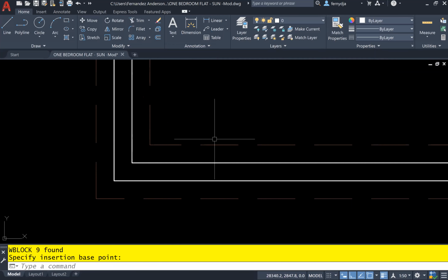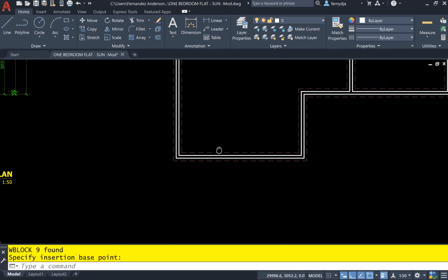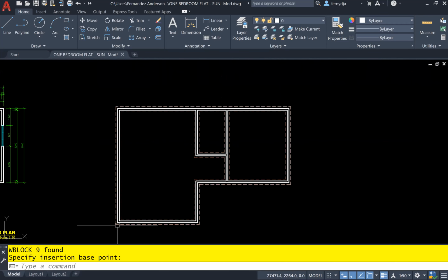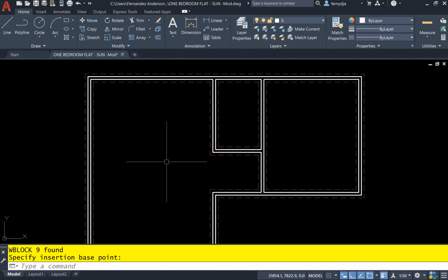So if you remember, if you're using AutoCAD 2019 and below, when you launch the insert command as I enter, it will give you the insert dialog box from which you can browse to your location, bring it in, assign your angle, and then insert. So you can only do one of each orientation at a time. So these will be the angles to insert them when we're ready: 0, 90, 180, 270. So you will insert one of each type and copy and paste into the other location.